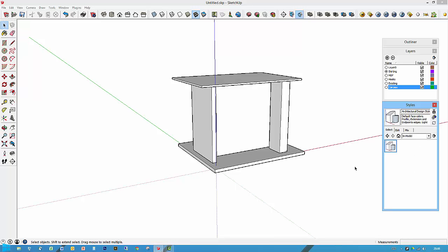To get rid of any that you don't want, you can click on that and purge unused if you've got any that you don't want to retain in your model. You can always drag them in later. They reside in folders and files elsewhere, so they're not affecting the actual geometry or the style makeup in your model necessarily. You can always bring them in, and it doesn't matter what you do to the ones in the model, unless you save them out and overwrite the existing ones, then they won't change either.